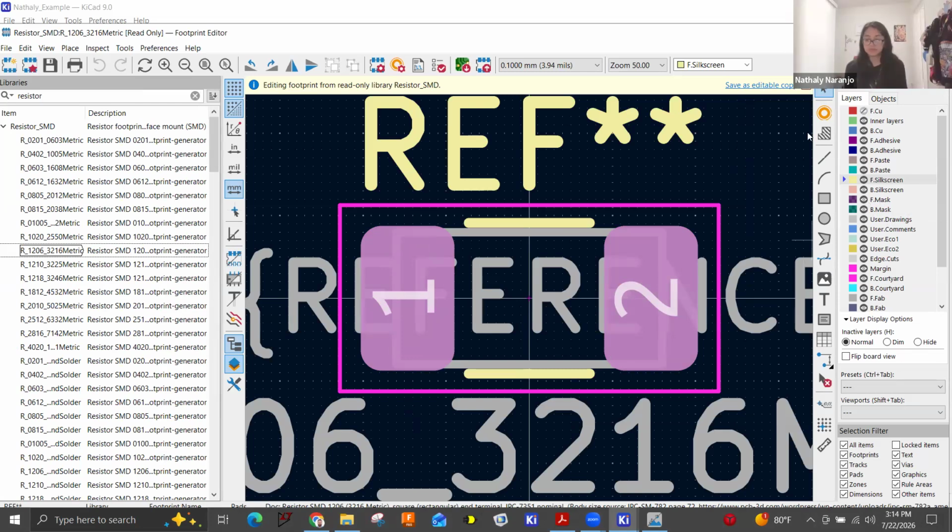Okay. So it makes sense that anytime you're going to be soldering a component onto the board, you need to remove the solder mask because the solder mask is there to protect the other copper from getting hit with solder. So when we're actually going to do soldering, they want to know where are you going to be soldering and we'll remove the mask for you. But it's important to note that these footprints that come built in, they have that layer already removed